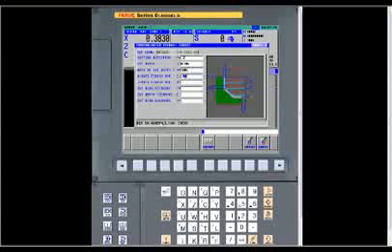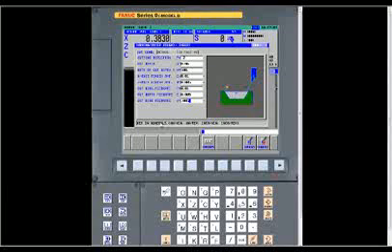So I always leave 10 thousandths per side. Then 5 thousandths on the shoulders, 0.005 input. And this is our feed rate again, 0.01. And then this is our relief feed rate, 5. And then this is when it comes out of relief, 0.005 there also.